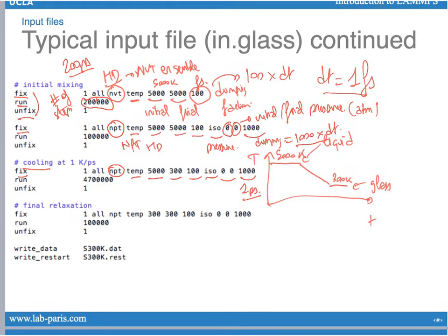This means that here you start your fix, you start the simulation in the NVT ensemble, and you call this fix 1. This is the name of the fix. LAMMPS will continue to do that for 200,000 steps. And as soon as you put the command unfix, with the name of the fix command that you put, this will cancel the constraints.